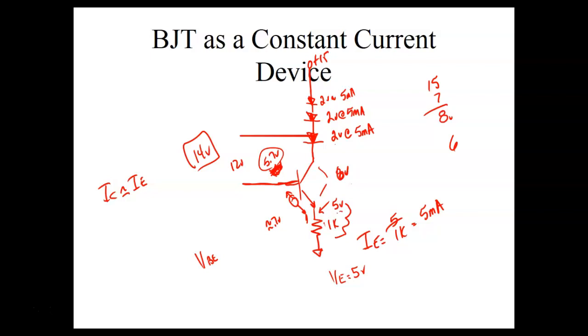NiCad batteries, if you still use those. The problem with NiCad batteries is that they get a memory, by the way. So if you got NiCad batteries, guys, you don't need to leave them things charged all the time. NiCad was the first rechargeable battery they came out with, and there's still a lot of devices. So a NiCad battery gets a memory, which means the more you charge it, the faster it runs down. So with a NiCad battery, you need to charge it up, run it till you get a low voltage warning, charge it back up, and then that's okay.